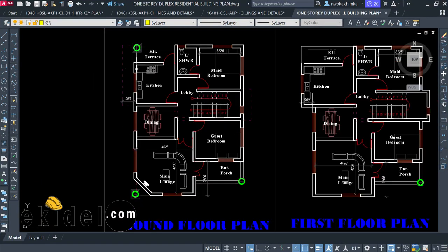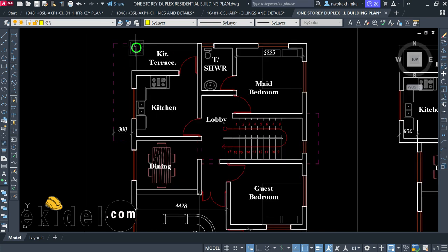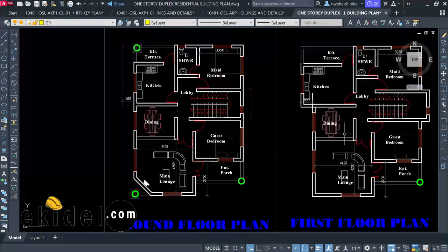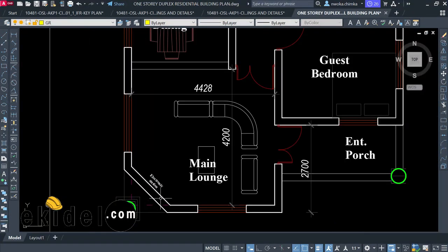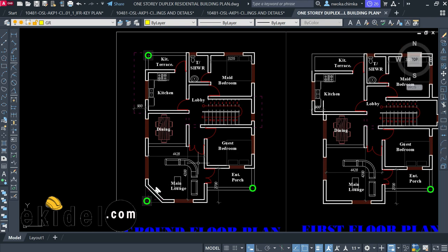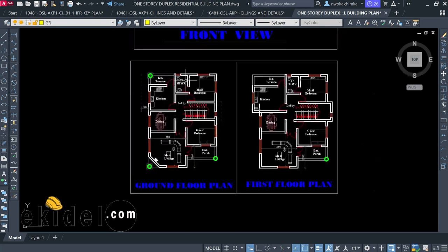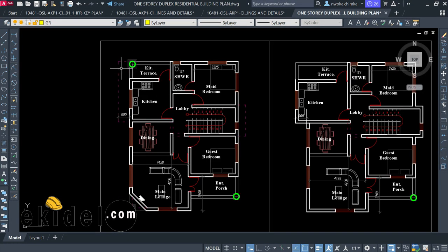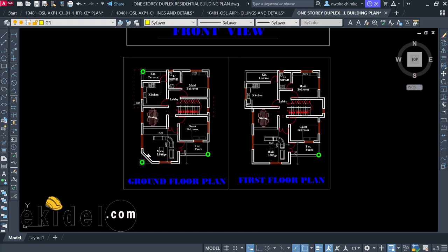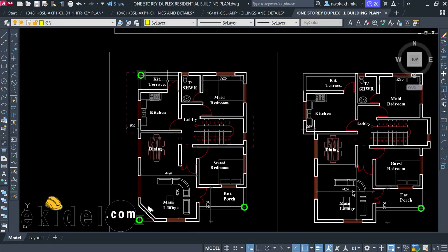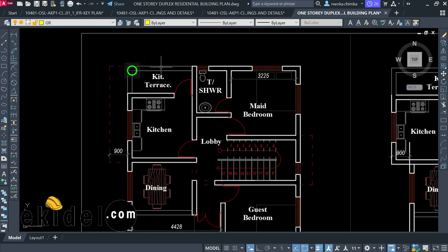Okay, so right now, since I've known that there's a cantilever and also circular columns stopping at the slab, and also there is an inclined section here, it is now time for us to begin our GA drawing. Your GA drawing is to be done on the ground floor. Like I said, GA drawing simply means column positioning, paneling, and also how your beams are going to run. So I'll begin my GA drawing now.